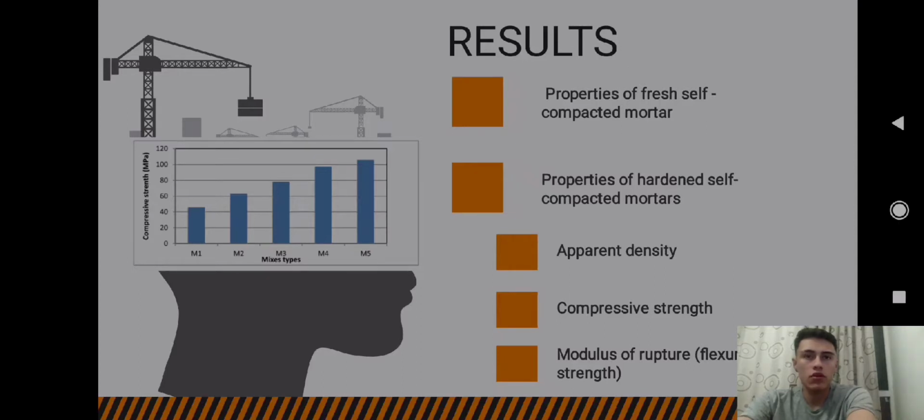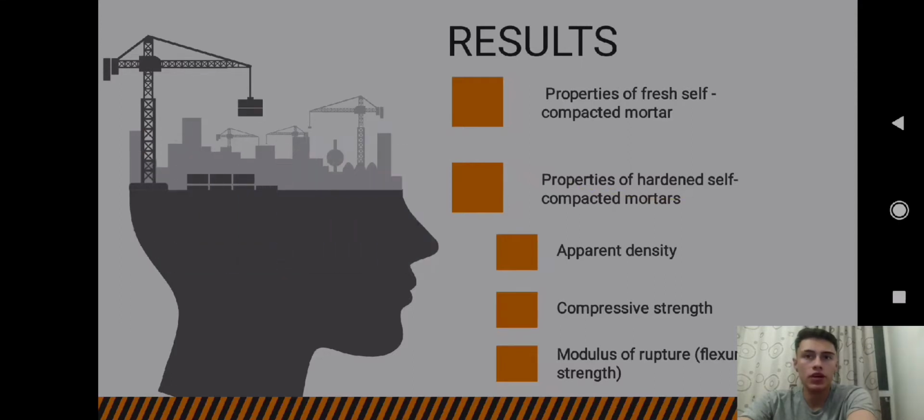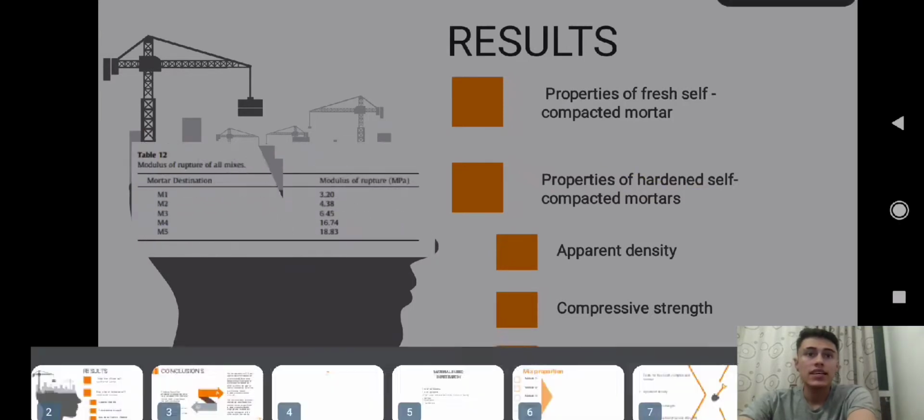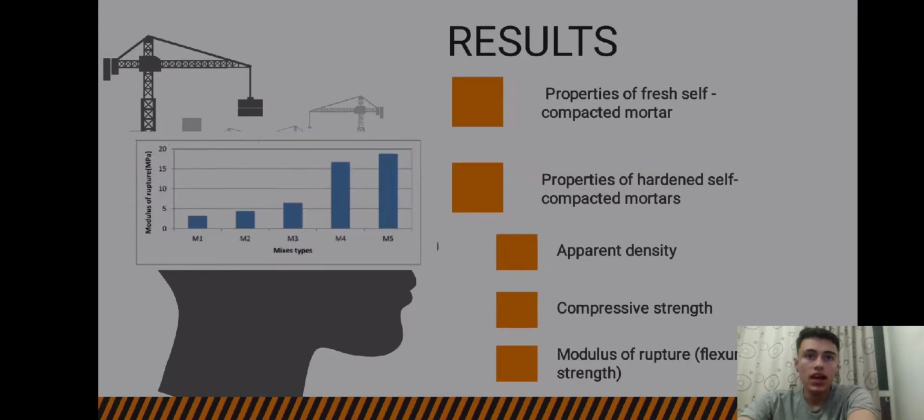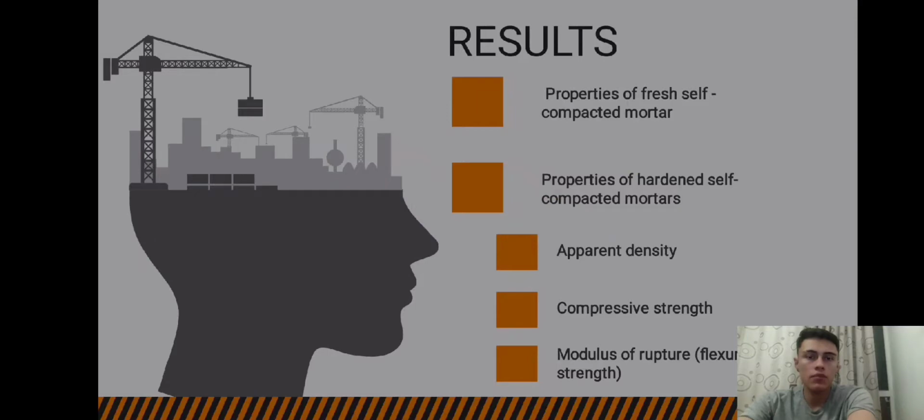Another result indicates that the use of superplasticizer causes an increased compressive strength as the water binder ratio decreases to 0.28, which causes a high reduction of porosity of the hardened mortar and therefore an improvement in compressive strength. On the other hand, the substitution of 8% by weight of the cement by silica fume induced a further increase of the resistance of the mortar to compression, and the inclusion of the microsteel fiber in the mixture improved its compressive strength due to the effect of the steel fiber in bridging micro cracks, and consequently leads to a higher strength of the composite.